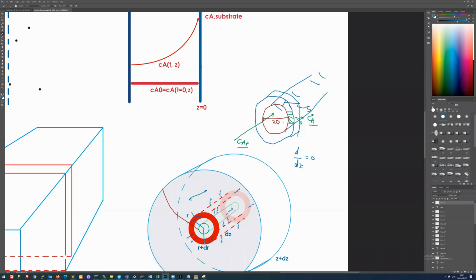And clearly we are talking about cylindrical geometry now. We are talking about R, Z, and theta. So we know it's varying in the R direction. That's what we sketched out here first. We said the concentration is going to vary across the thickness of that O-ring. So we know that is going to feature. For Z, we've made a couple of arguments now that possibly we could get away with not using Z.